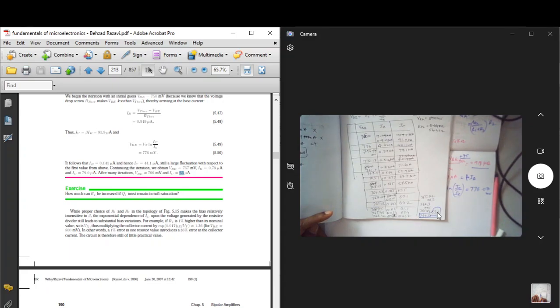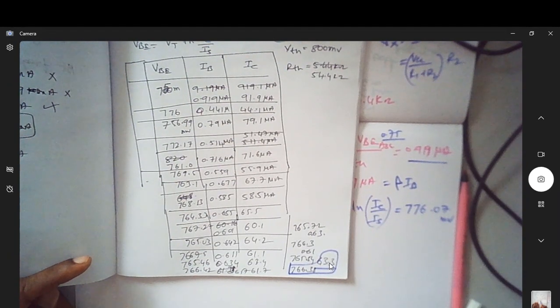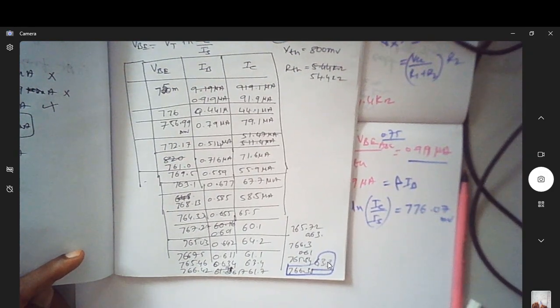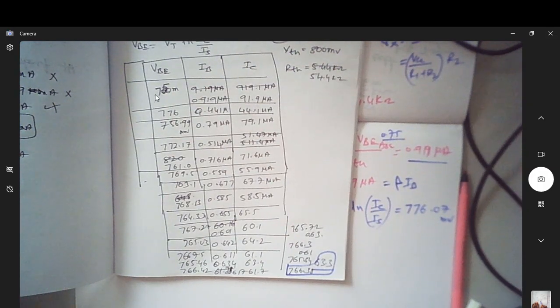Can you see this is coming out to 63 here? Can you see it is 63? So this 63 came after so many iterations. Now you can see after this comes, it hangs around 63 microampere. So this is what is called the number of iterations, so that your assumption of VBE, which started with 750 millivolt, will settle down at 766 millivolts. That's what is the iterations required.